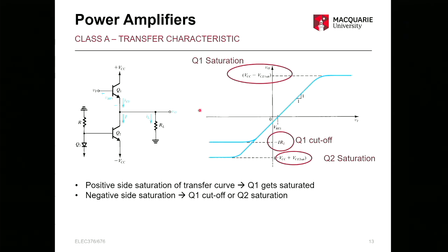So depending on your load resistor, that will change the negative cutoff. If we want a full class A, to use the maximum range of that output, this is a condition we want to meet, to ensure that this line is matching or below this point. Then you're really just limited by the transistor saturation.